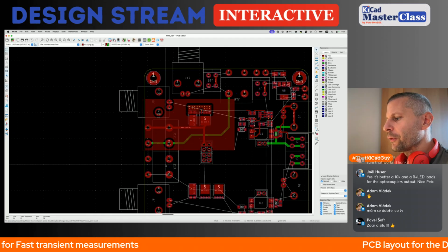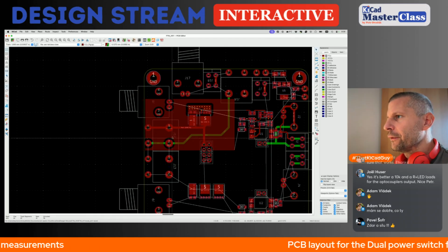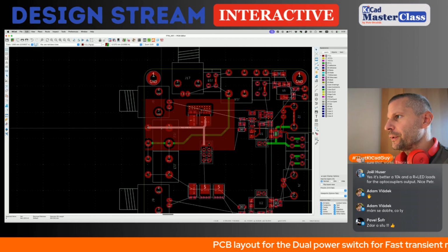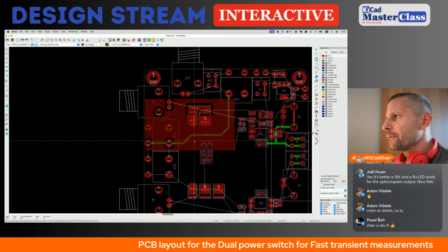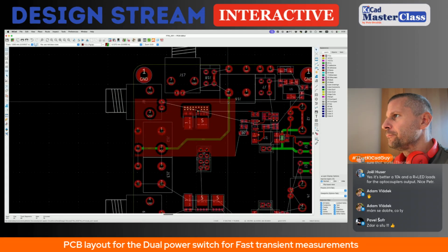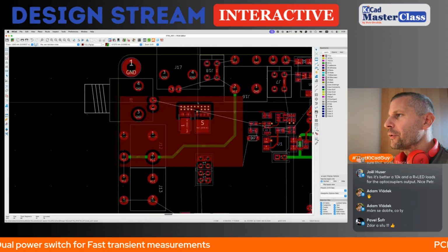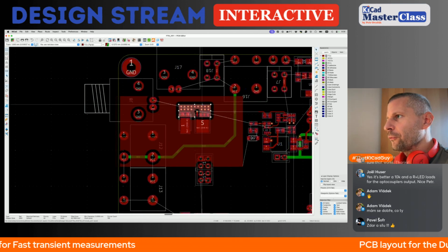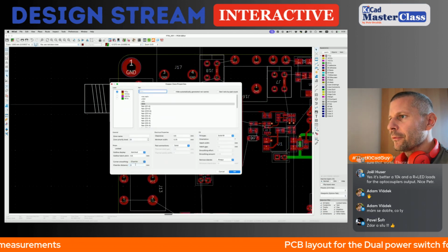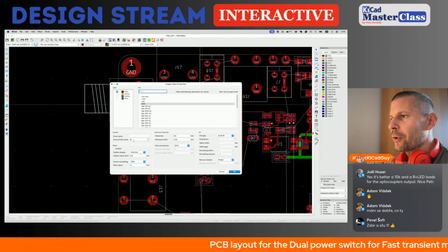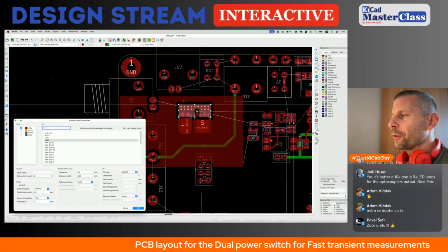the VCC will be connected on the bottom side, that's okay. I can remove this track. Yeah, the reason for this, where I changed the priority to 20, is that it's a polygon inside the polygon.